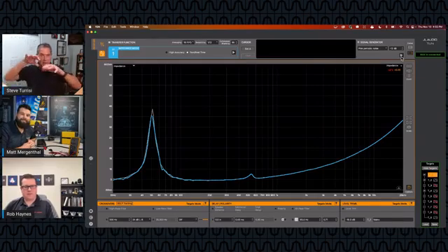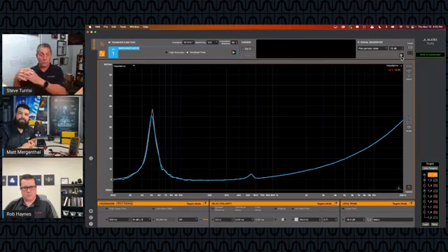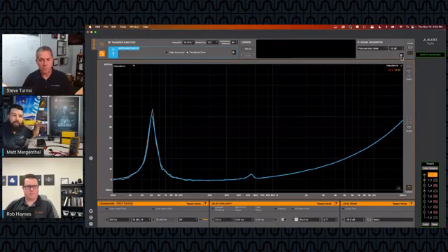And as each one hit, I could see the fluctuation in impedance pretty visibly. I did the same thing on a big woofer, and very little, if any, change at all because of the relative change compared to the mass of the speaker. With the smaller drivers, the difference was much closer, so it showed up a little bit more. And I think that might be what you're referring to. At higher frequency, some of these fluctuations and deviations are going to be more prevalent. For sure, yeah. This has a much heavier mass and cone assembly than a smaller driver would. So there's a lot of things that'll show up.